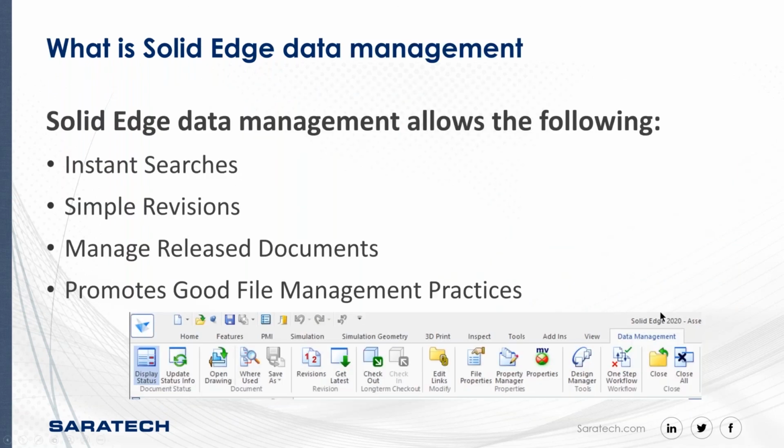So if we look at this, inside the data management toolbar, we have the where used. If you open the where used, you can see every document recursively that it might be used in, drawings, assemblies, and then you can make your engineering decision as to whether or not you want to revise the upper level assembly of the parts used in.